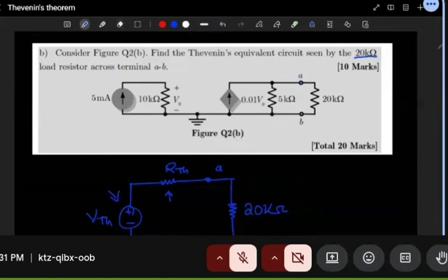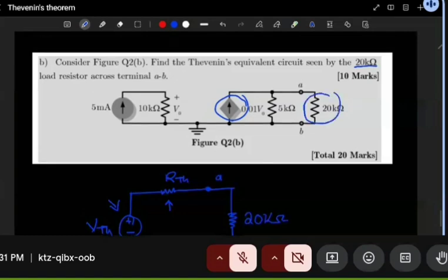Now, what do we do? In the presence of a dependent source, we actually don't go right ahead to find the Thevenin's resistance. We have to take an in-between step. We have to get it indirectly. So how are we going to do that? The first step is still the same. We need to open the load resistor. So we will draw the circuit without the load in place. To do that, of course, you will have to redraw the circuit. Perhaps let me just make the redraw.